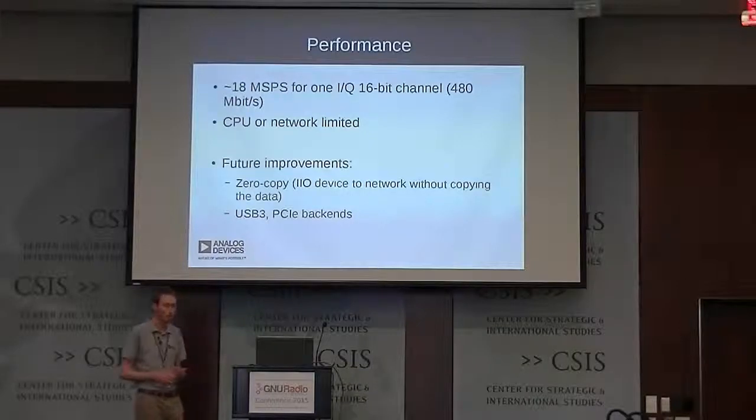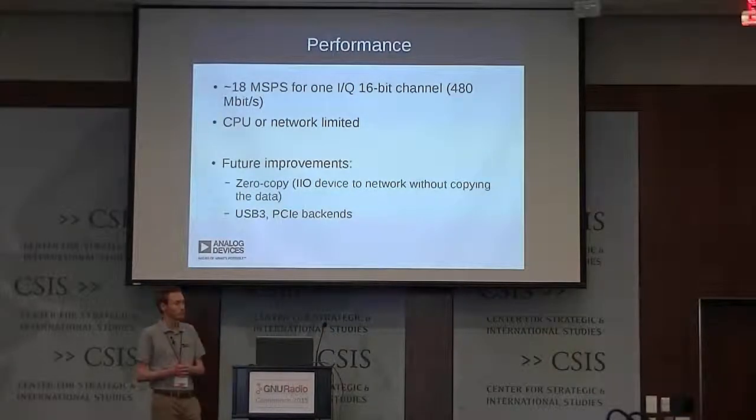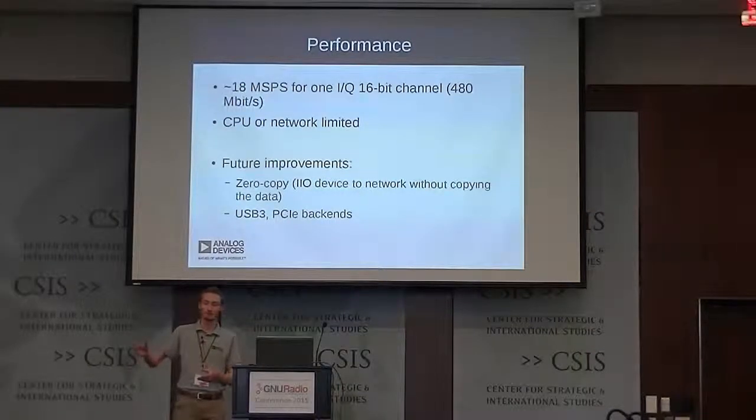So we have ideas to improve that. The first one is to reduce the CPU usage on the target board using zero copy techniques. Zero copy means copying the data using DMA from the transceiver to the memory, and then directly using DMA from the memory to the network.